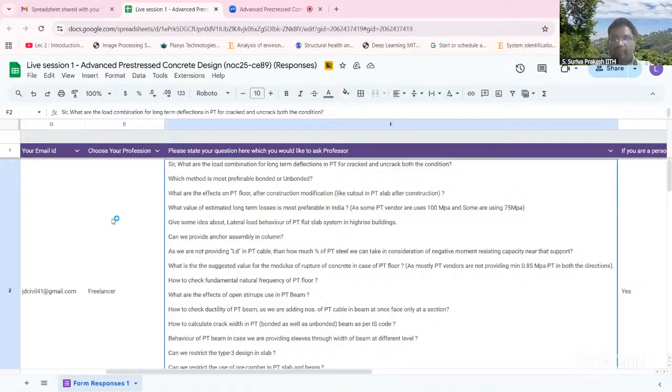Mainly, they are right. If it is seeing the dead load and it is giving the opposite effect, then it is okay. But having said that, for a beam of, let's say, 12 meters, I cannot have a 70 or 80 mm camber. Then what will happen? You end up providing more screed, and placing all your tiles will become difficult.